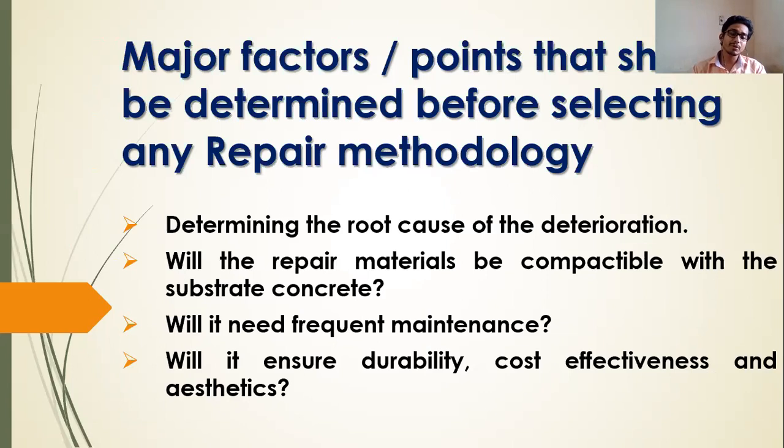The third point is, will it need frequent maintenance? I have also seen that if there is a structural crack, it may be in a beam or in a slab. If there is a structural crack, then how much can you repair if you don't control the loading, or if you don't give any extra support to take the extra loading?